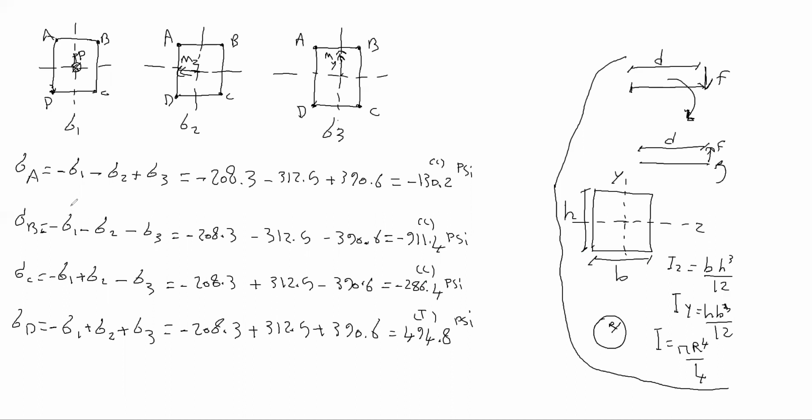All of them are negative, which means if we change sigma 1, 2, 3 from point B to any point in this quadrant, all of them are negative, there is nothing to cancel. So the stress in this quadrant is always non-zero. But look at the signs in A, C, and D. At least one of them is positive, which means if we go from A to another point in the first quadrant, at some point this positive cancels with these 2 negatives, and then we reach 0.